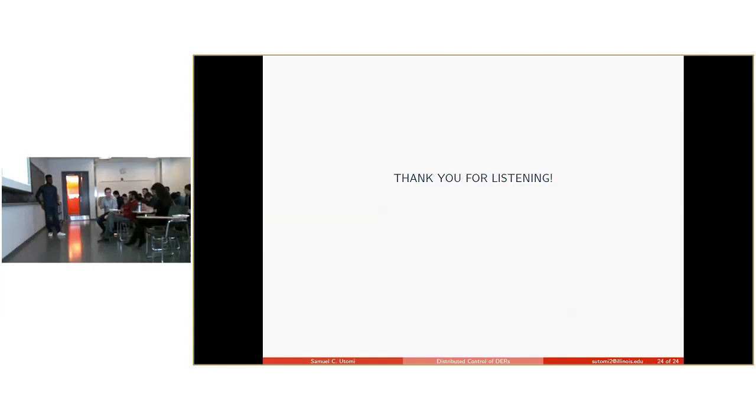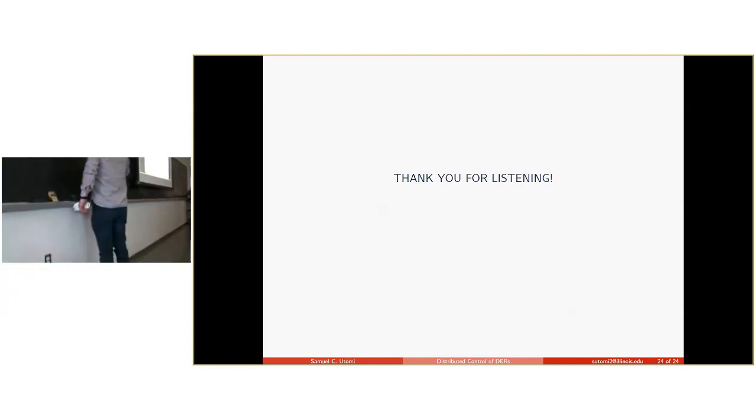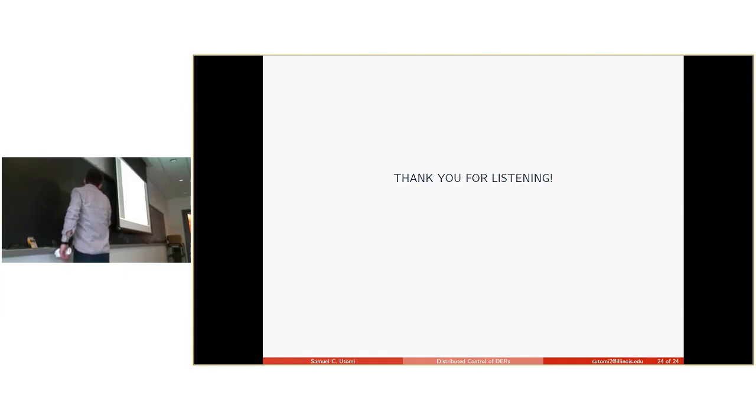And the other two controls, what you call primary and secondary, are still simulated. You could push those out of the emulator, have them sitting in an industrial grade controller, and have that interface on top of what we have as well. So right now, this is the HIL which has the power stage plus lower level control, and the box he showed there is basically talking to this.